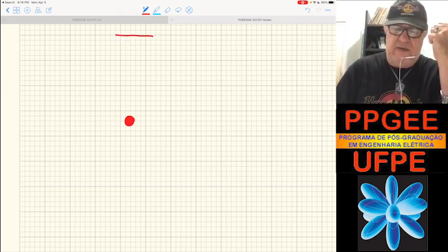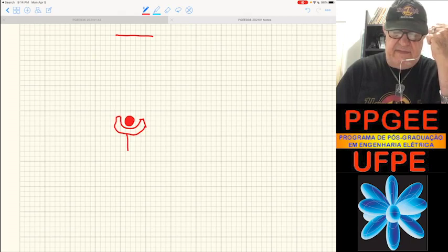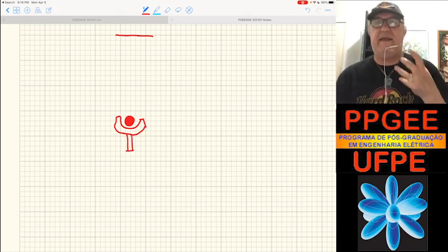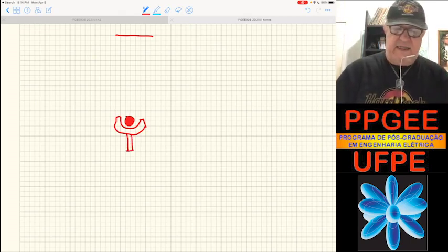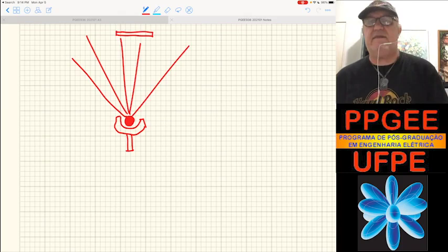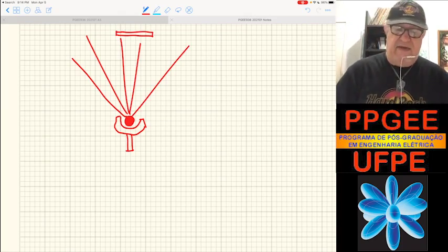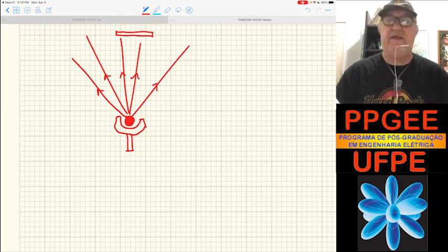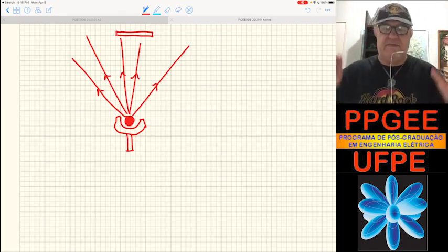You heat it by putting it on a holder that is heated. Then it evaporates radially in all directions, and part of it is collected on this surface. So here you have a real source of diverging material.